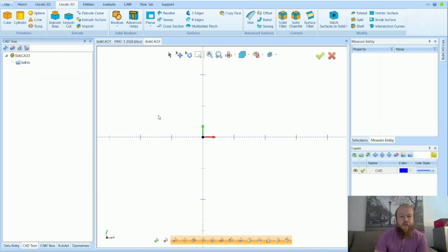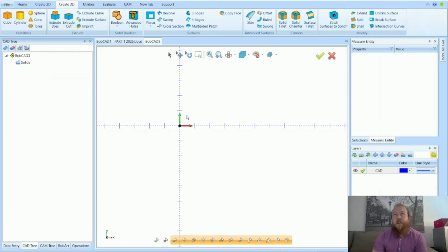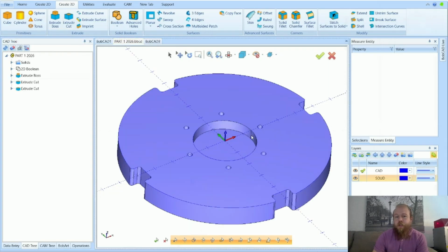And we're going to start with creating more of a curved shape so that we can do 3-axis milling. In this one, we're going to do the Mill Express functionality, which is 2-axis milling, where the end mill is going to come down into the pocket in Z, and then it's going to move around in X and Y, and it'll pocket everything out, and then it'll come back up in Z. So it's only moving 2 axes at the same time. That's what our Mill 2-axis will do in the Mill Express package.